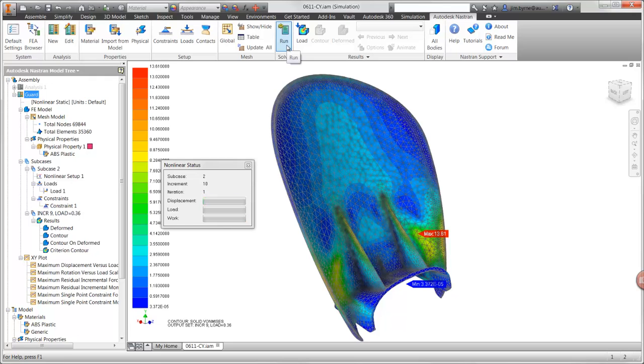You will also notice the results are displayed while it's being solved. They are also shown in the graphics view, as well as saved to a file so users can stop the calculation at any point and view the progress of the load. We can already see that the highest stress in the model is getting close to yield even before the solution is complete. This is a huge time saver, enabling designers to take notes early during calculation.